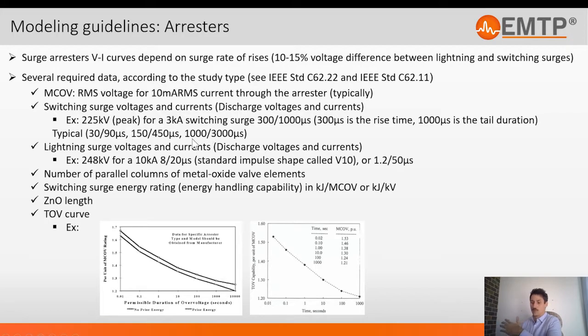So again, if you are going to use a surge arrestor which is not frequency dependent, so just a nonlinear resistance, and you want to study switching, then you may want to use, if you can of course, the points of a surge here, which will be similar to what you obtain by simulation. You can go back and forth, of course. It's not necessarily the easiest way to proceed, but that's a solution that provides fairly good results.